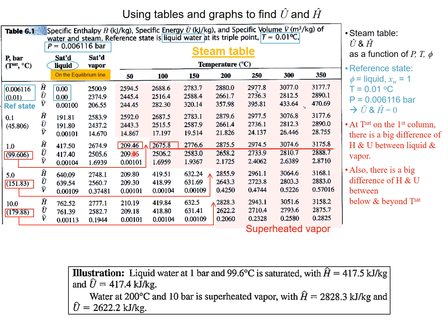Then let me increase the temperature. Right now we are at 50 Celsius degree at 1 atmospheric pressure, actually 1 bar. Then we are going to 100 Celsius degree. Before 100 Celsius degree, we are passing the boiling point, right? The saturated temperature, in other words. So at this point we are on the equilibrium. Then after passing this point, all of our water molecules go to the vapor or steam phase. Then those three values belong to the vapor of water molecules. Then 150 Celsius degree, 200, and finally 350 Celsius degree.